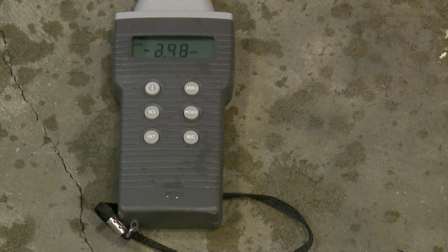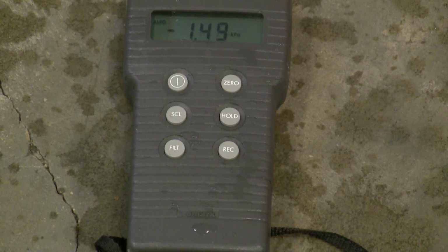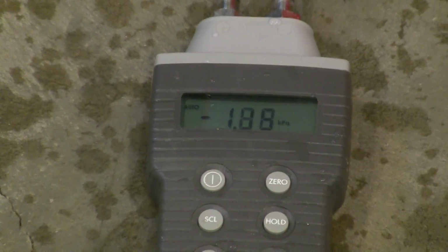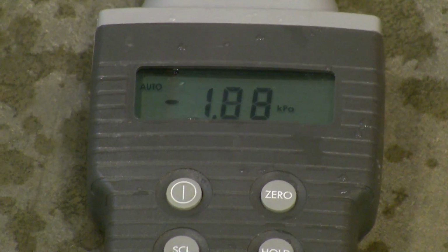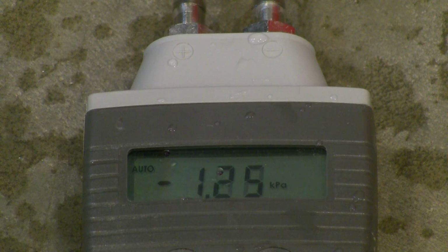Now, since that valve has just been exactly back to the same position as before, we can expect the same flow rate. The negative pressure measurement means that there is a pressure loss through the fitting, which is exactly what we'd expect to see: less pressure downstream than there was upstream. And so what you need to do is take some pressure measurements there.